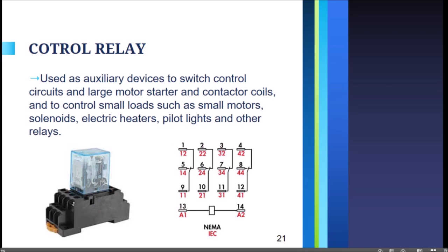Usually, if we are going to have our motor controlled by a PLC, programmable logic controller, the output of the PLC will be fed into the control relay, and the output of the control relay will be fed into the contactors.